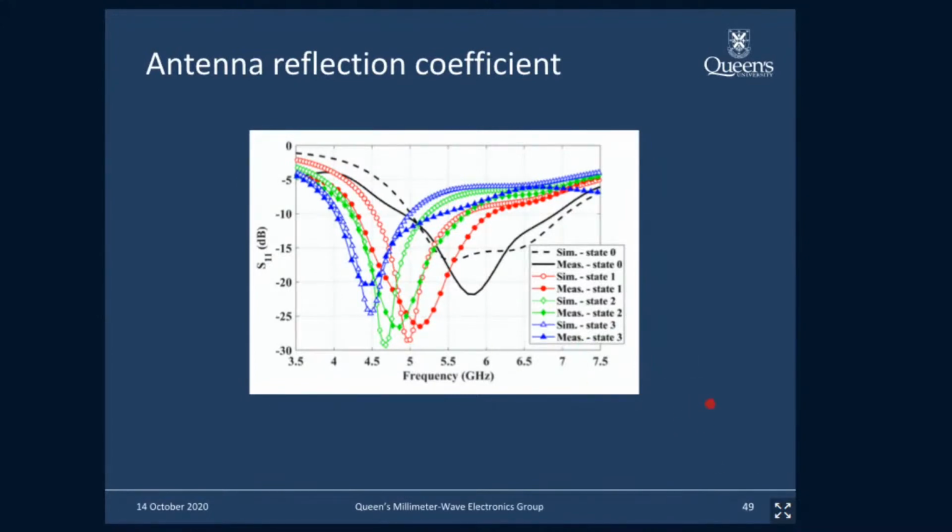So an antenna, when it's radiating, you send a signal into an antenna, right? And at the frequency at which it radiates, you want all the energy. The energy is leaving the antenna, going to free space. So you expect to see a low reflection coefficient when you look at that port at the radiation frequency.